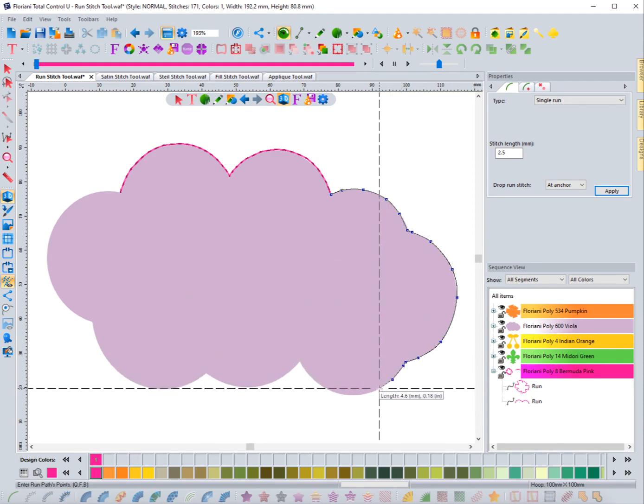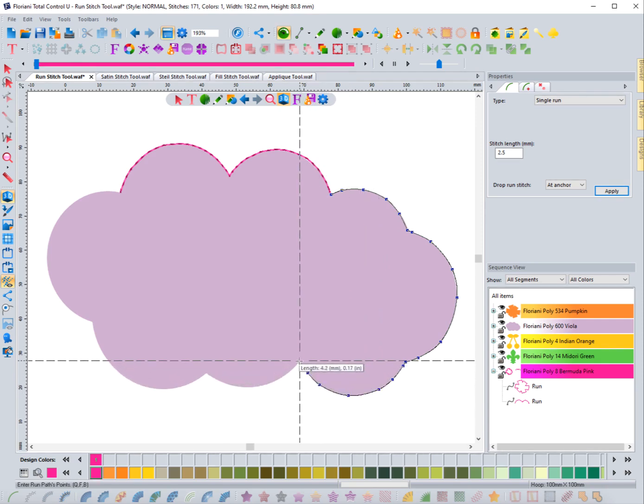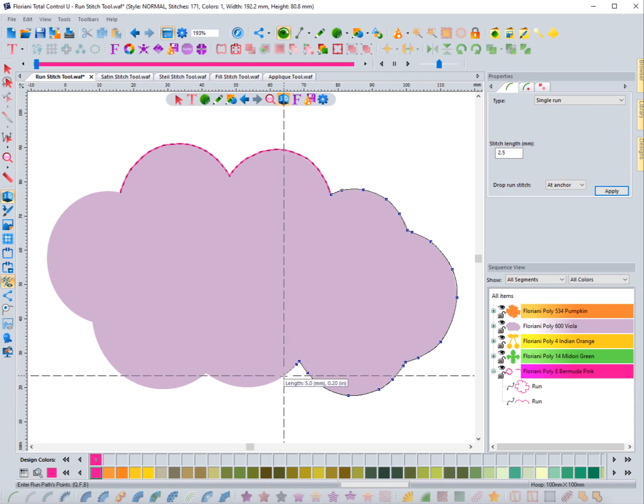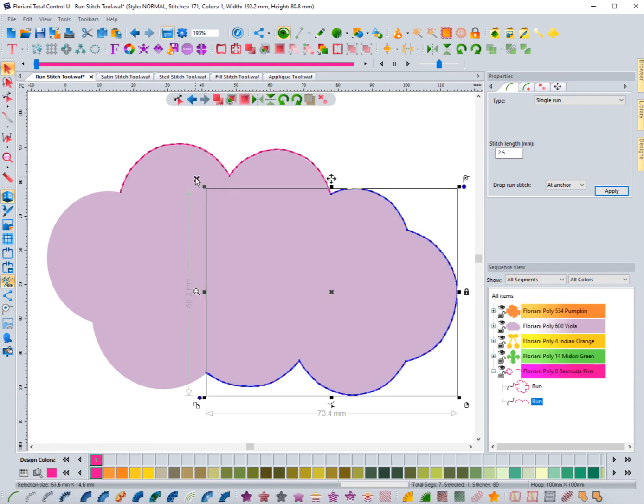Now I can hold it down again and click around this curve shape. Again, I'm going all the way. I'm even holding down control for that one. Now I release it, drop a stitch without control being pressed. And now I'll hold down control and click the rest of them. So it just takes practice, and it's not difficult. It's just you have to know that if you're going to change a direction, if you've been using a curve holding down the control key, you're going to need to drop that little stitch there without holding control down. And that's going to allow you to get that look you want.